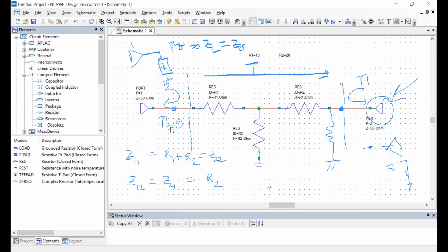And if you just connect the attenuator's port to port 1 of the network analyzer, which is the instrument used to measure reflection coefficient, and you forget the other port, and by forget, I mean either you have not connected it to the second port of the network analyzer, which is a 50 ohm system, or you have not put a 50 ohm termination on it to make sure that the full circuit is complete.